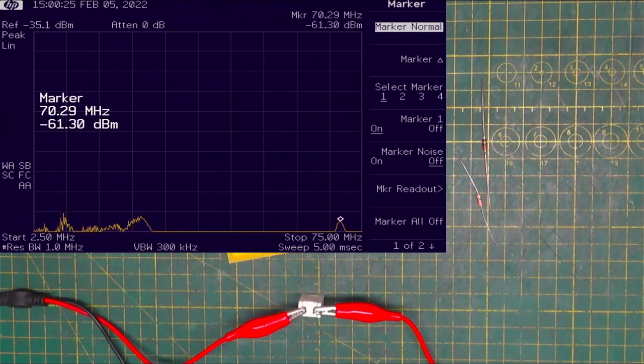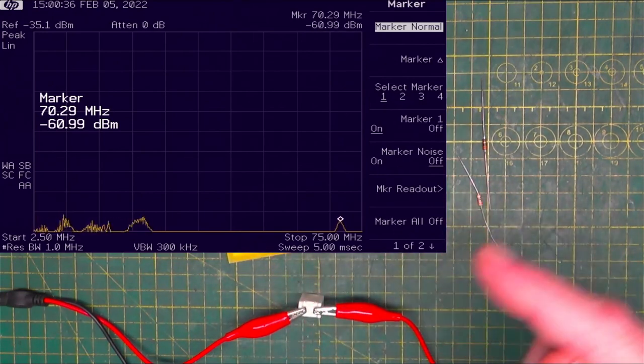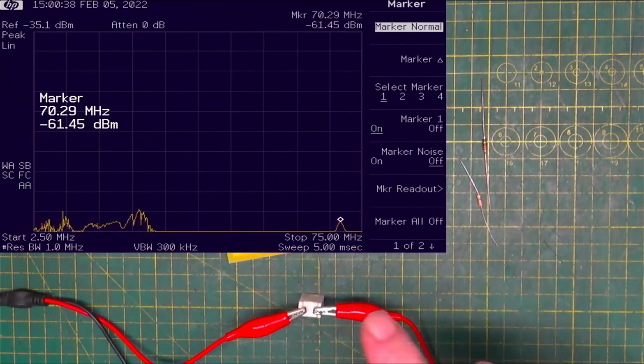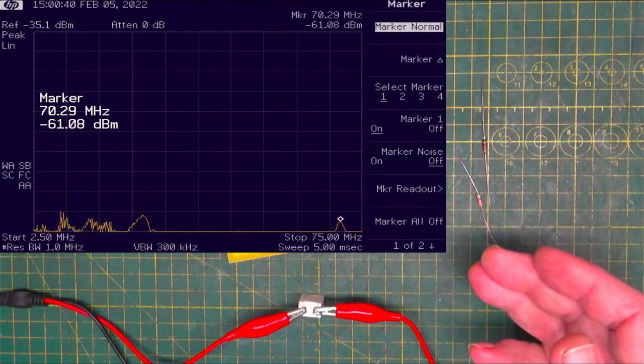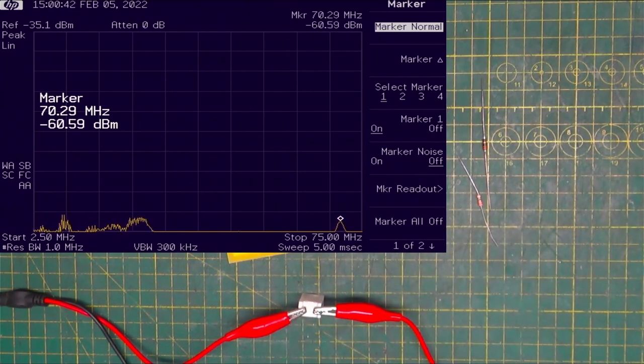Well, there's a reason for that. This is a wire wound resistor. And basically, it's a form with a bunch of wire wrapped around it. Nichrome something, I don't know what they use in these actually, but there's a bunch of wire wrapped around it, and that wire wrapped around that form creates an inductor. This is an inductor doing what inductors do at frequency.